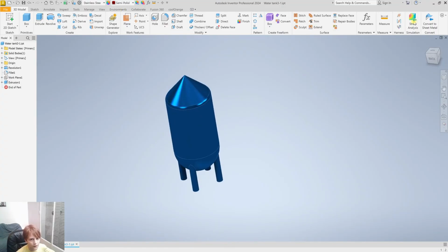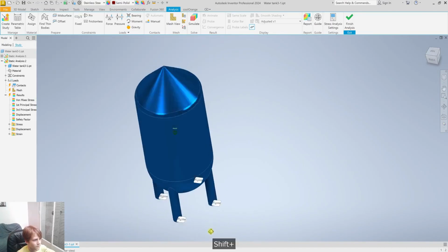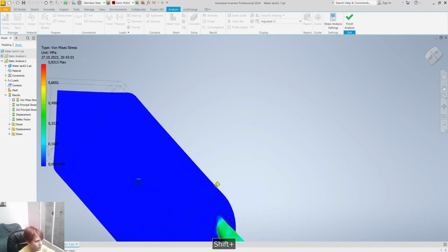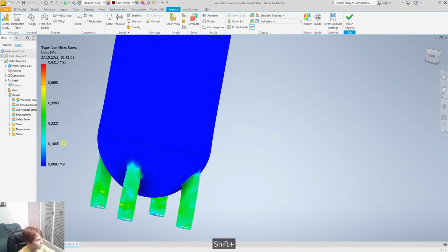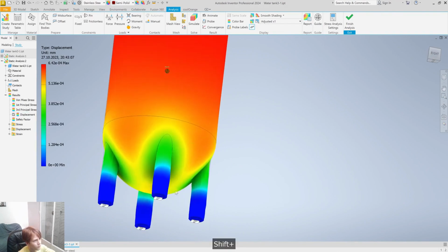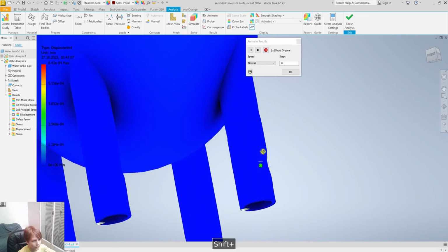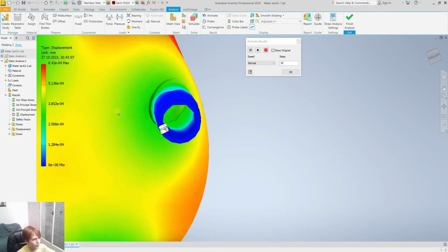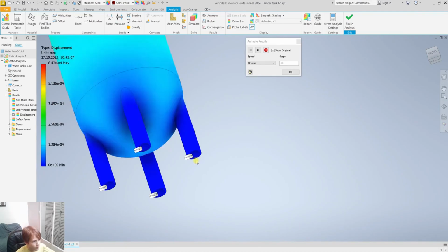Let's go to stress analysis. We'll leave everything as it is for now. Simulate. And it will compile the mesh for us automatically. There, it has recompiled the mesh. Let's turn on displacement. If we look at the animation, we can see that the legs have deformed quite a bit. But if we look at the scale on the left, we see once again those same negligible values. So the legs have barely deformed under the barrel's own weight.